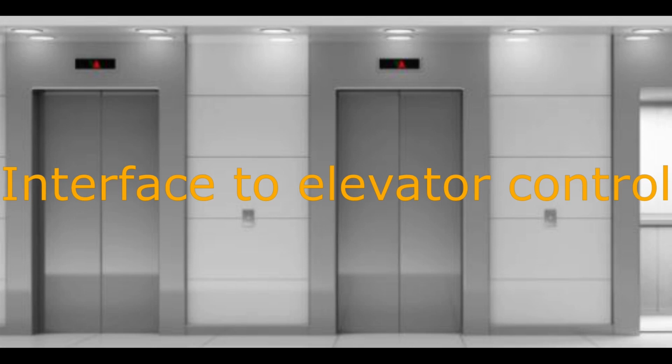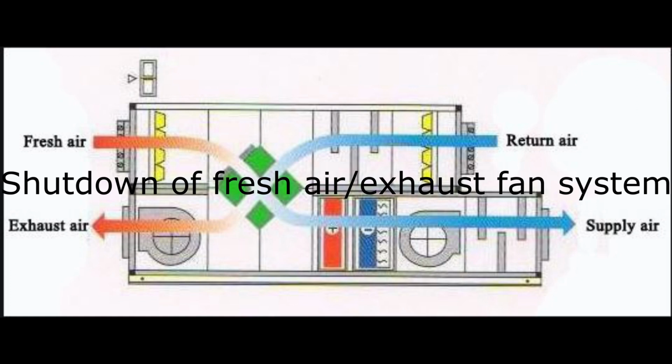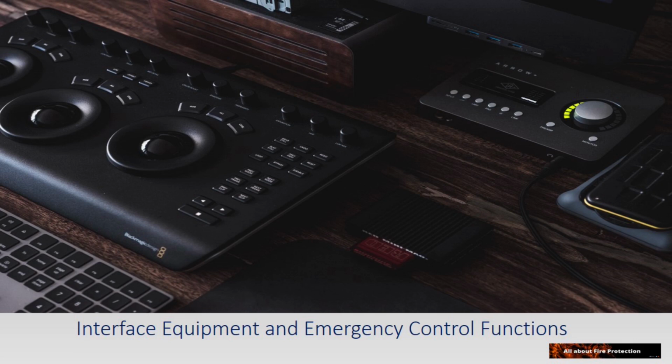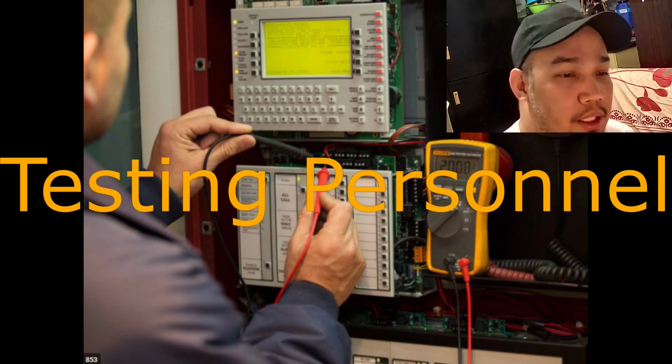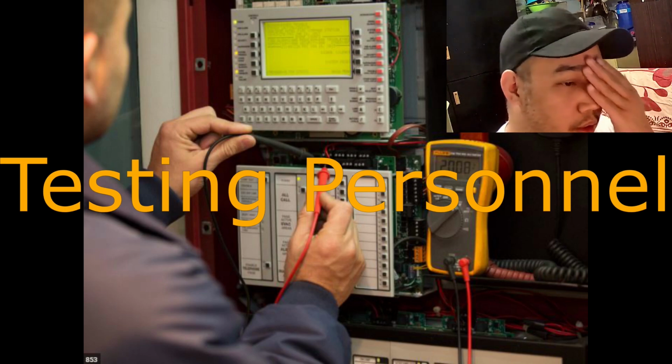5th, interface to elevator control. 6th, interface to smoke control. 7th, shutdown of fresh air or suppression system. And many more, depending on which systems are installed within the building. Testing personnel shall be qualified and experienced in the arrangement and operation of interface equipment and emergency control functions.